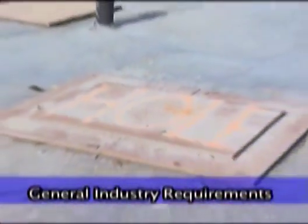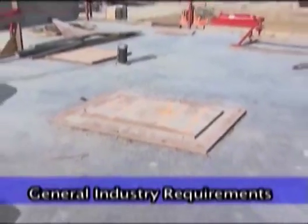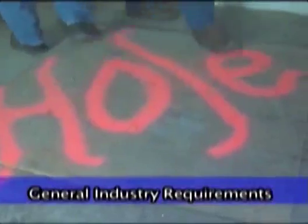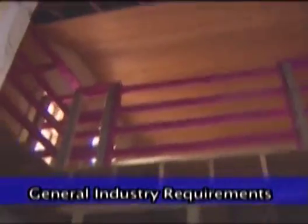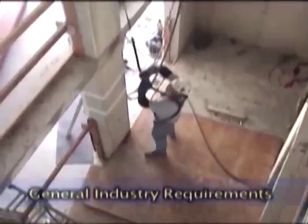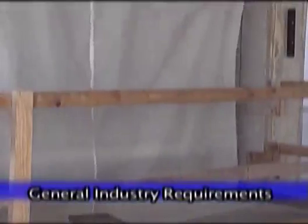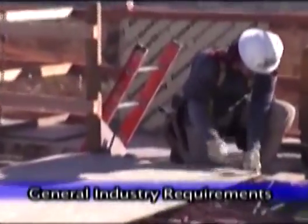All floor openings measuring 12 inches or more in its least dimension should be covered or guarded to prevent people from falling or stepping into the area and/or materials from falling into the area. Floor openings include the following: skylights, stairways, ladderways, hatchways, pit and trap doors, manholes, and temporary floor coverings. Every floor hole should also be guarded by either a standard railing with toe board or be covered by a cover of sufficient strength and construction.